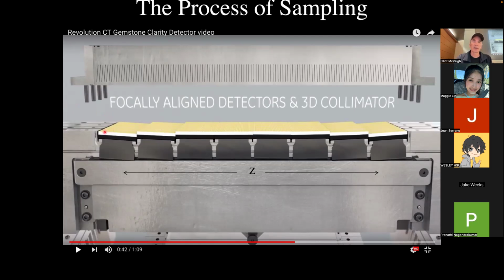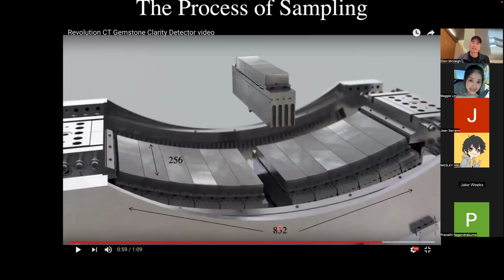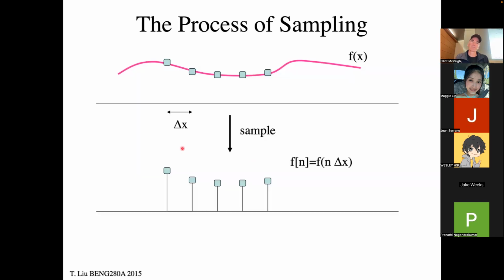So here, each one of these little chips, I might have a picture. Yes, I do. So you lift one off, and it's like 16 by 32, 1 by 1 detectors. A little flash would happen. That flash goes down here to a photodiode, and the signal goes off to the computer. Ring! I've just detected an X-ray, right? And you've got a whole field of these. You can see the kind of picture that you've got there. And we plop it back down in there and make our 2D sample array.